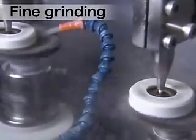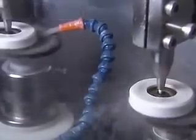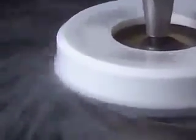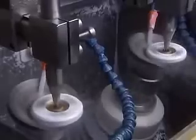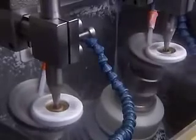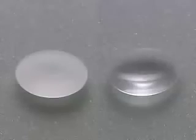Following rough grinding, the lens is subjected to fine grinding. The surface of the lens is ground with high precision using an artificial diamond pellet platter to attain proper roughness and surface curve. To reduce the time factor and enhance the precision of the polishing step which follows, precision in the order of 1/1000th of a millimeter is required during this step.